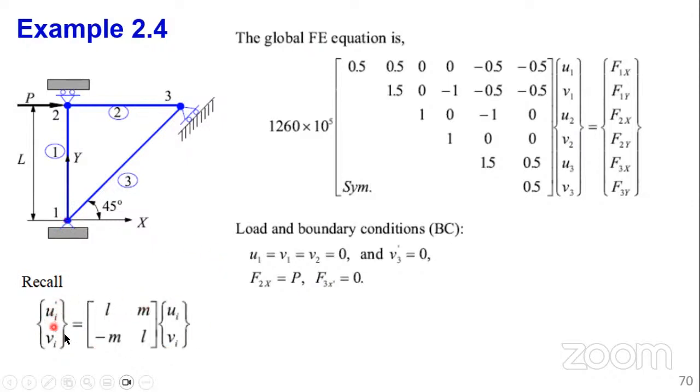This is what we derived as the equation, and this matrix is the one we call the transformation matrix T. So we are going to trace this equation because we have nodal elemental quantities, not global. These are the ones that we want to transform from local to global.